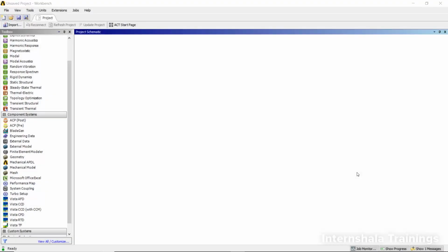In this lecture, I am going to introduce you to ANSYS Design Modeler. Inside ANSYS Workbench, we have two types of geometric systems. One is the Design Modeler geometric system, and the second one is the SpaceClaim geometric system. If you want to create simple components and edit data that has been imported from other CAD systems, you can efficiently use this geometric modeler or Design Modeler. If you want to create advanced parts and advanced assemblies, then you may use SpaceClaim.